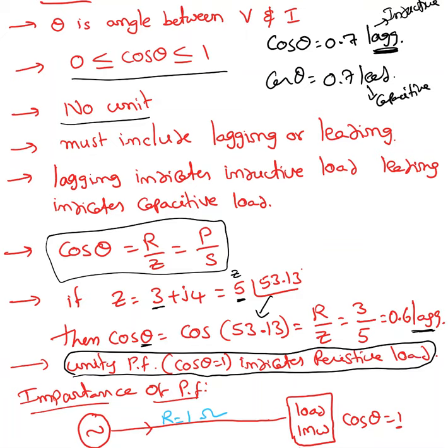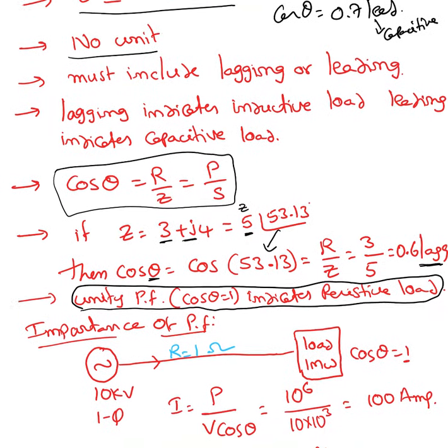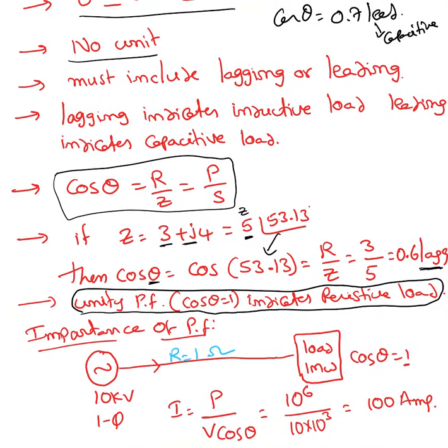I'm saying lagging because I can tell this is an inductive reactance. Whenever you see inductive reactance, that's a lagging power factor. If it is capacitive reactance, then that is a leading power factor. And as I mentioned, unity power factor indicates it's a resistive load.